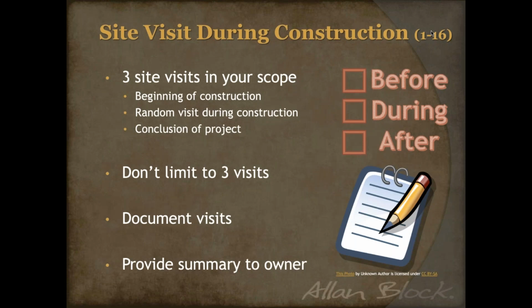Now, moving on to site visit during construction. The reason that we have this is basically it's great to check in on your project. We say that each of you, when you design a wall, should visit at least 3 times on the project. One at the beginning before the project starts, one random time during the construction, and then one at the conclusion of the project.